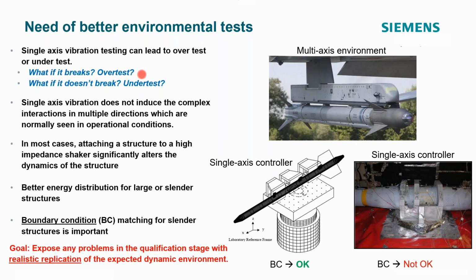You always want to have these questions in your mind. What if it breaks? Did I over-test it? Or what if it doesn't break? Did I under-test it? You always have to keep those questions in your mind when you're doing these types of environmental tests. Single axis vibration does not induce the complex interactions in multiple directions, which are normally seen in operational conditions.